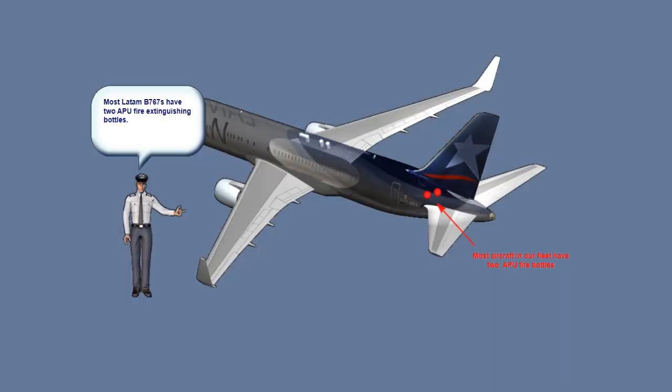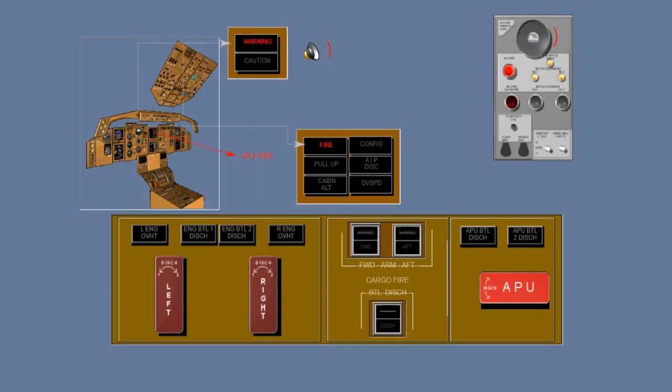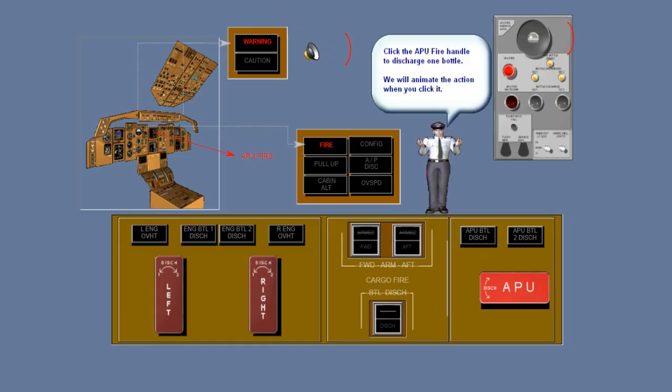In the event of a failure of both loops, a fault indication is provided by the sysfail light and ICAS advisory message of Fire Overheat System. Pressing the sysfail switch light will reset the system to monitor other detectors.